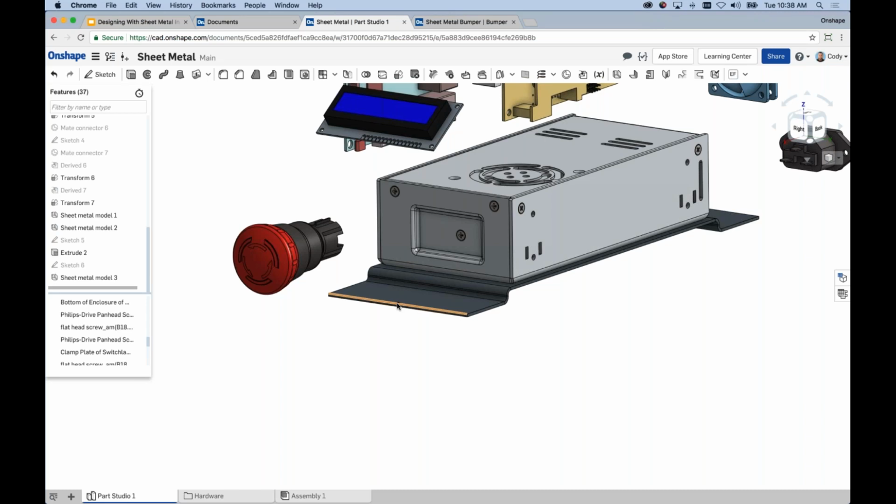Modifying the original volume updates sheet metal parts. Yes. And that's one of the benefits of this kind of master model technique, is that the initial solid block drives a number of parts, potentially. But yes, if you change the initial block, the sheet metal parts will update because they're driven by it. There's a parametric relationship between the two.